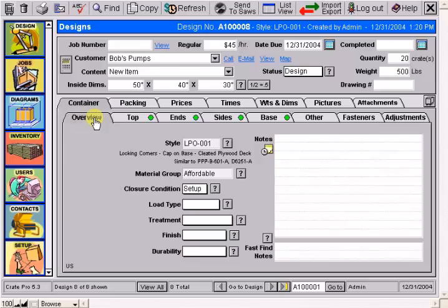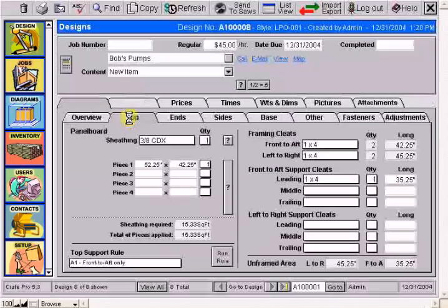In CratePro, you can change most any piece of material individually, or by using automated features, you can change lumber bases to plywood, vice versa, change fasteners and have them automatically respace, or even see rip values to assure your lumber fits properly. Here's an example.